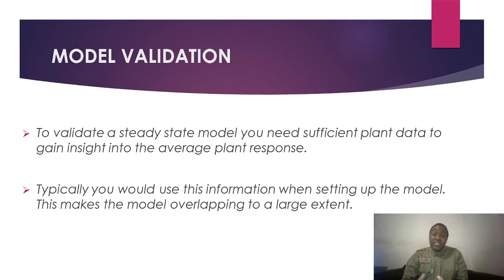To validate a steady state model, you need sufficient plant data to gain insight into the average plant response, in the sense that for you to find if that steady state model, which is based on mass and energy balances, is a correct representation of the design that you want to construct. So there is need for sufficient plant data to validate that model.